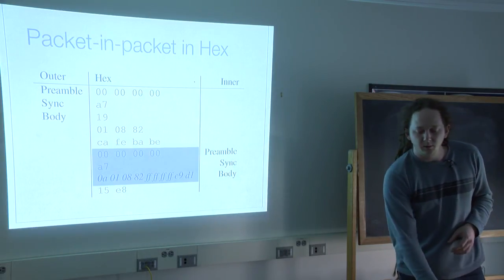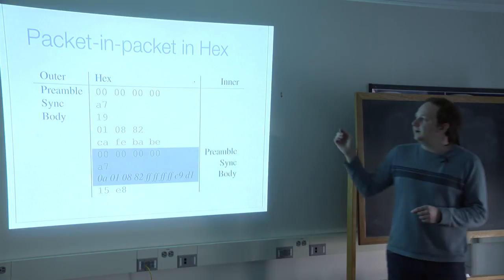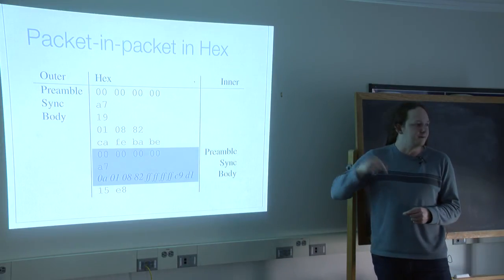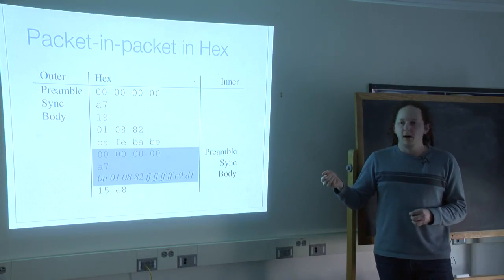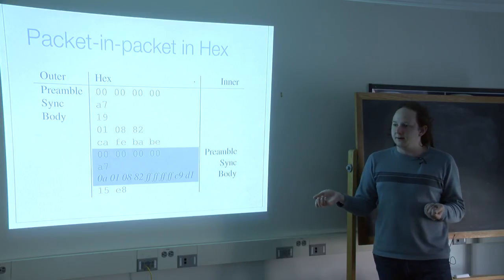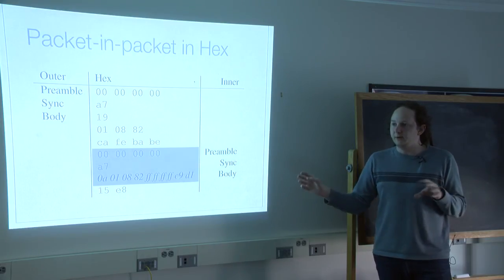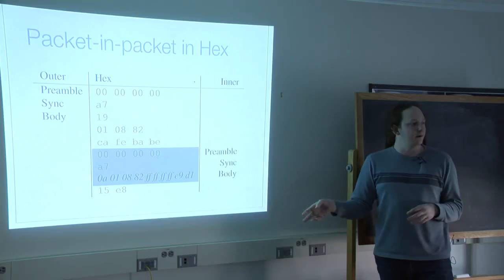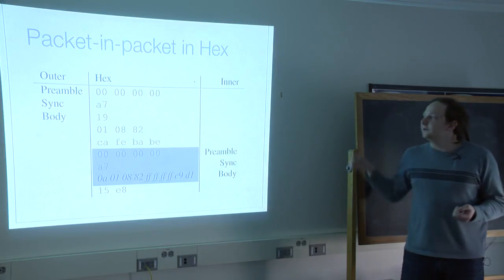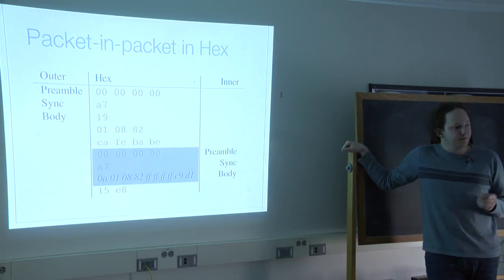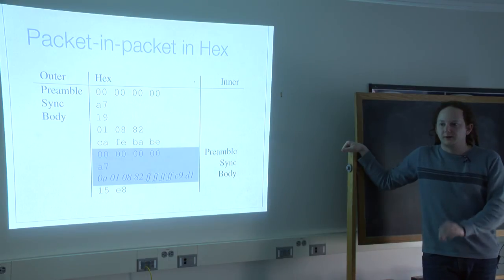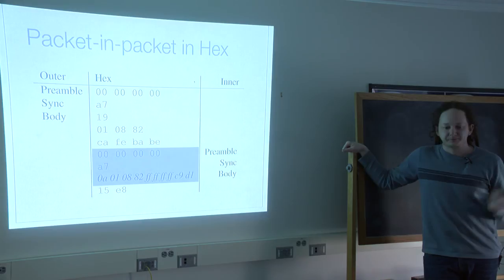So the way that this works in the real world is not that there's a random symbol error, which would be the appropriate way to model it if you had a clean radio channel with no interference, or you were transmitting over a cable. What happens is that there's a frame collision, which is how the 2.4 gigahertz spectrum suffers daily. So this laptop does Wi-Fi, but it also does Bluetooth.